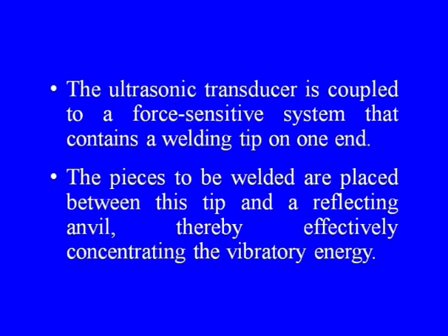The ultrasonic transducer is coupled to a force sensitive system that contains a welding tip on one end. The pieces to be welded are placed between this tip and a reflecting anvil, thereby effectively concentrating the vibration energy onto the zone of interest where the welding is to be carried out.